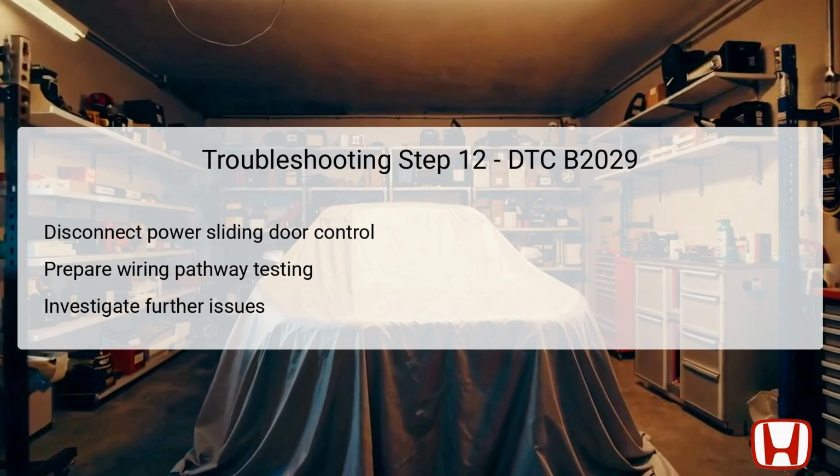This gives technicians a chance to examine any wiring impacts, ensuring there are no physical damages, corrosion, or loose connections obstructing proper operation. By taking this methodical approach, professionals can gather more accurate data, building a clearer picture of where issues are actually occurring within the electronic systems governing the sliding door functions. This isolation is key to understanding how to effectively repair and restore functionality to the system.